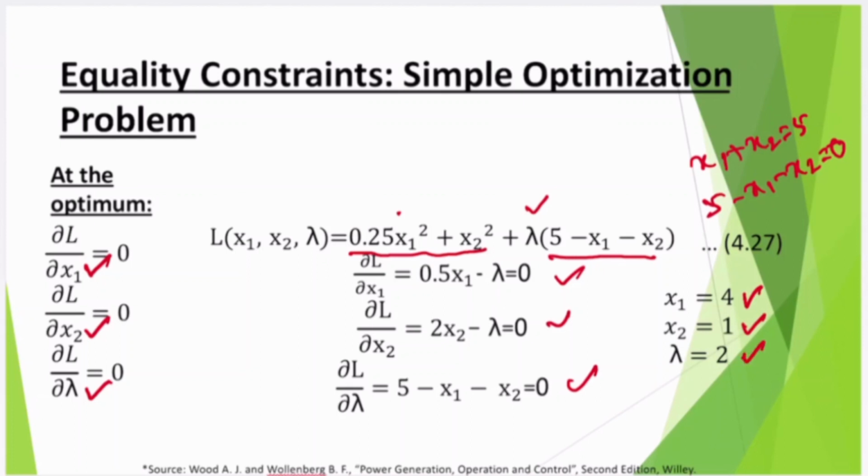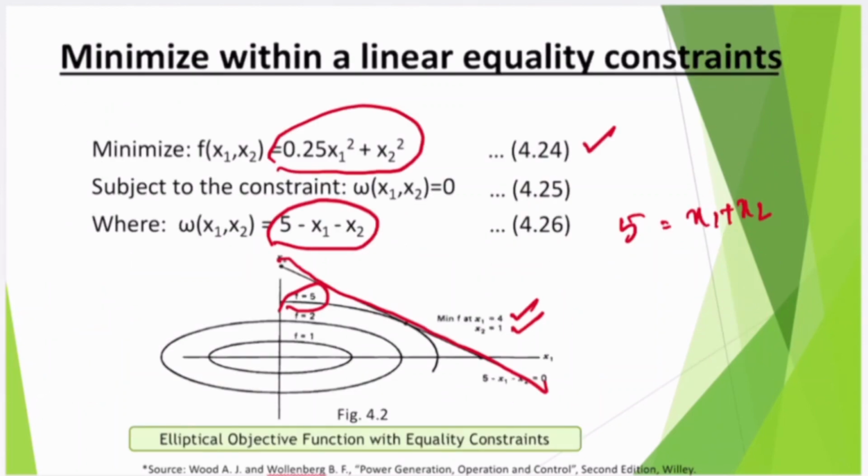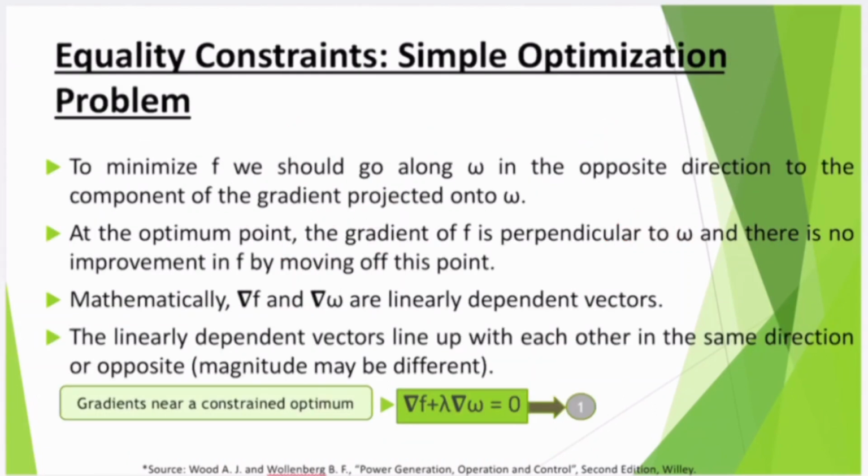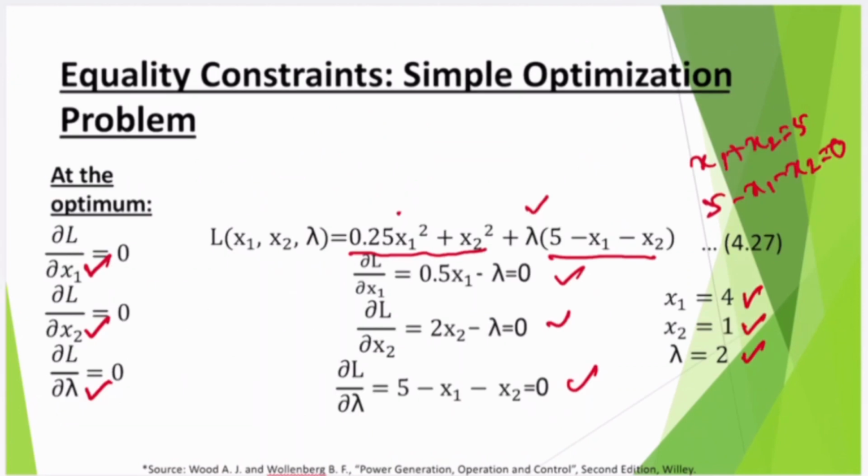So probably you could see that whether you use the Lagrangian multiplier, or you use the linear equality constraint equations, they both are satisfied. But in power systems, we'll try to solve most of our equations through this method. Okay, I will try to emphasize a little bit here. In power system engineering, this x1 and x2 are nothing but majorly my variables P1 and P2.